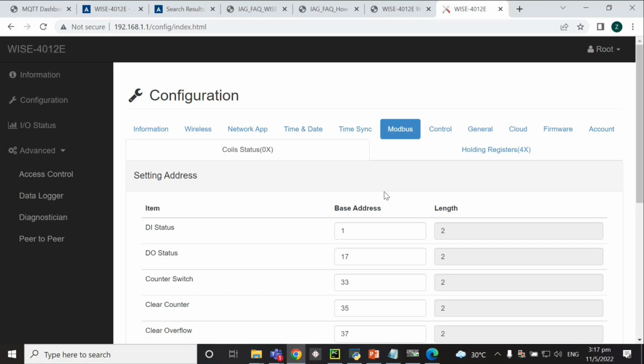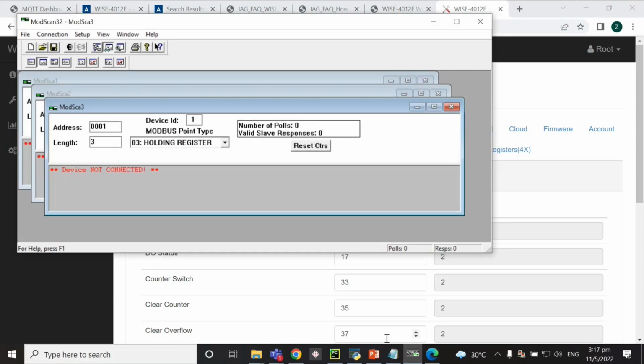Modbus itself. Before I move to exact addressing, I will slightly explain what Modbus is and what the data types are. Modbus itself has 4 data types. You will see coil status and input status. Actually, they are exactly the same. If you look at it from the signal point of view, we have digital and analog. What is the meaning of digital? Digital is the change of the state. They only have 2 conditions.